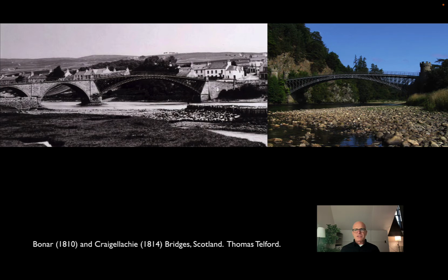And Telford's standard approach was to think about the cast iron bridge as an arch and a deck and a web. The arch in this case is all cast iron elements that are doing most of the work, carrying most of the load in compression. The deck is designed so that it has the gentlest slope possible for the carriages that are going over it.